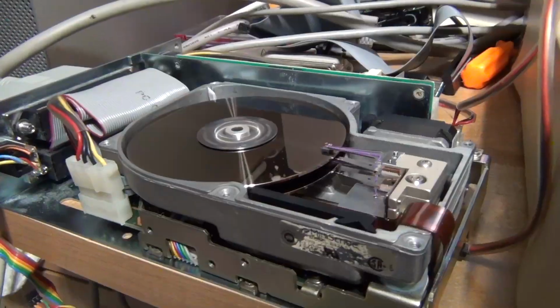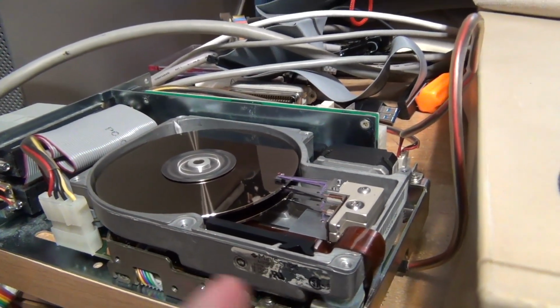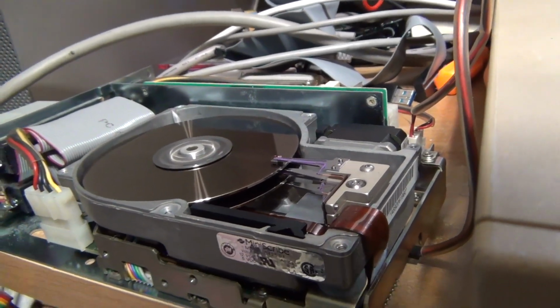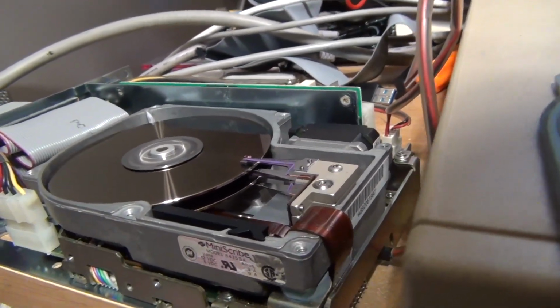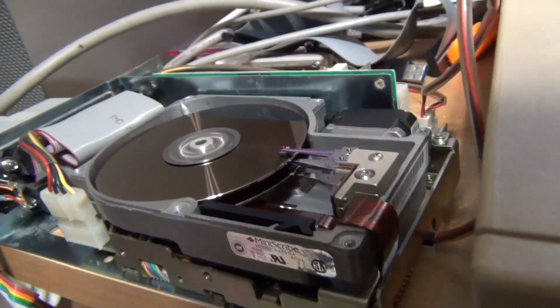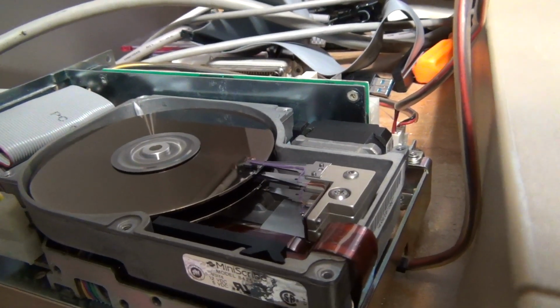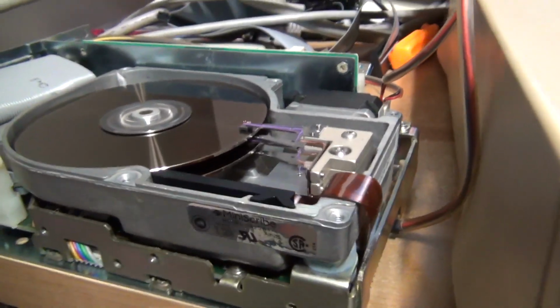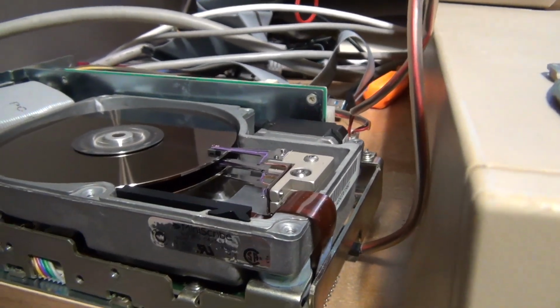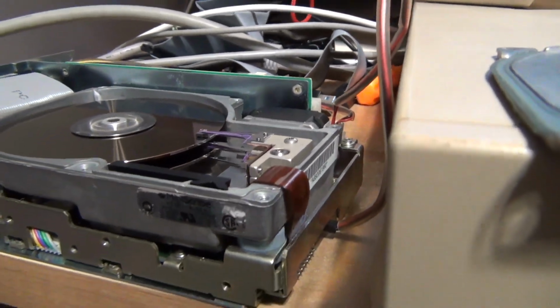There it went. I like that the head is on a linear track. Seems like a very Miniscribe thing. I've seen a few videos online that are like that. I'm hearing a little bit of scraping. It's probably just dust on the platters. It could also be what killed the drive. Honestly, no telling. There are I guess 5 heads? There's 3 head arms, I should say. Probably 5 heads.